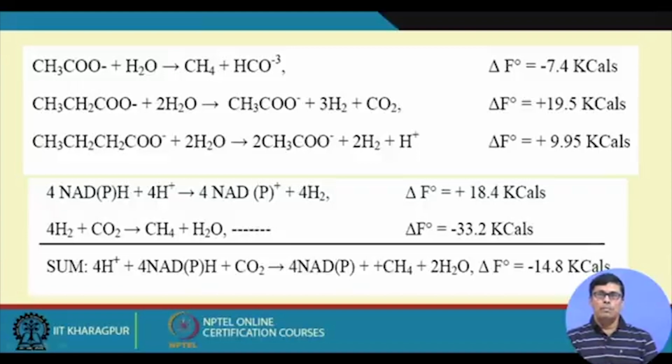So, it has been observed that when we operate any kind of anaerobic digester for a longer period of time, there will be accumulation of propionic acid in the reactor. In the long run, as you operate for a longer period, propionic acid accumulates in the reactor because propionic acid degradation will be very poor.